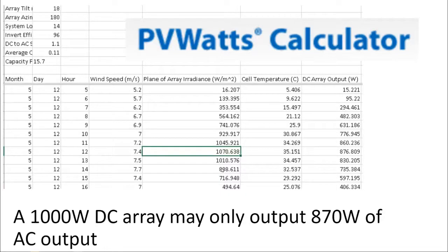How do you determine how many solar panels go onto a particular circuit when they are wired up to a particular inverter? Inverter manufacturers provide online software to assist this design process. They take the specific information from the module specification sheet, such as the voltage, amperage, and temperature coefficients, and use that information to suggest configurations which are compatible with their product.